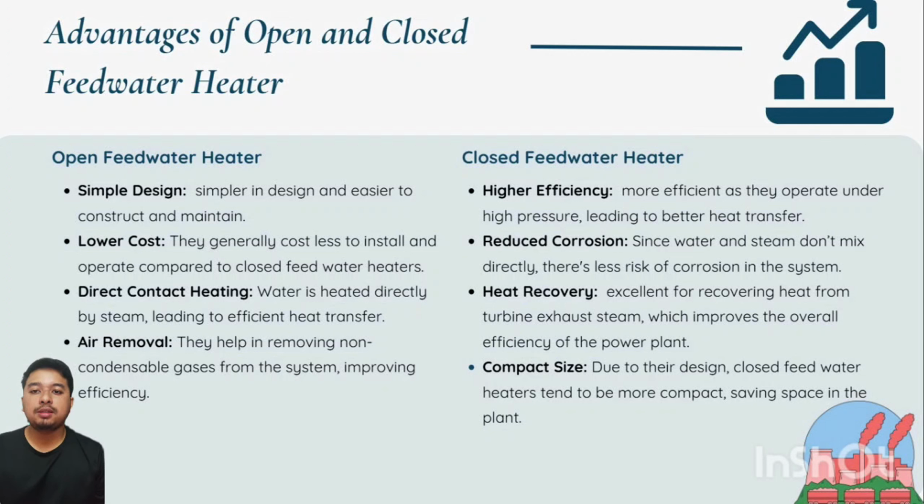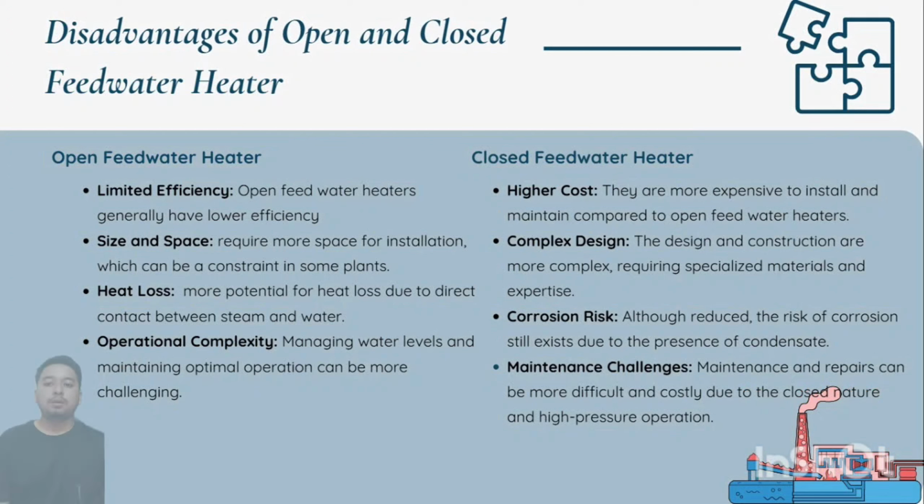Lastly is compact design. Due to their design, closed-feed water heaters are generally more compact than open-feed water heaters. This makes them ideal for power plants with limited space, as they can be installed in smaller areas. For the next slides, I will present the disadvantages of both feed water heaters. First, I will present the disadvantages of the open feed water heater.